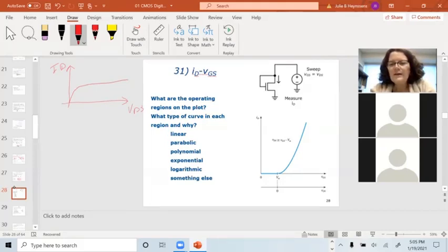Basically, VDS equals VGS because VD equals VS. Those two are tied together, so they're constant. Is VDS greater than VGS minus VT? VDS equals VD equals VG, which means VDS equals VGS, which means this, and that's a negative sign, and VT for an NMOS is positive, so that equation always has to be true.